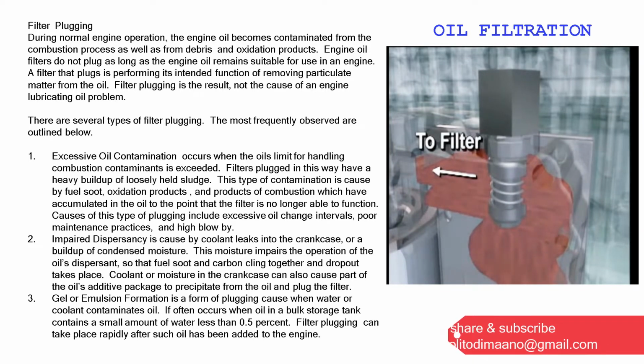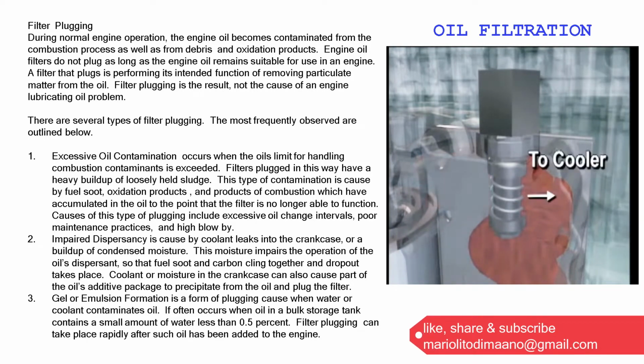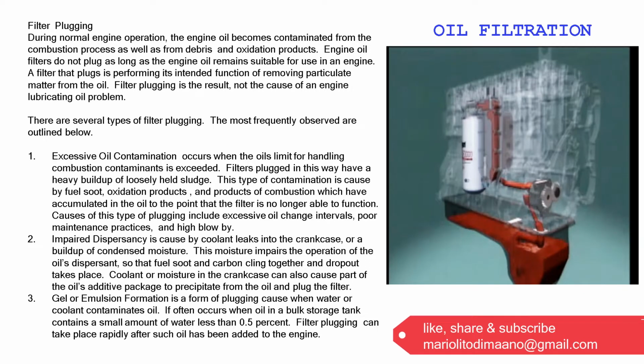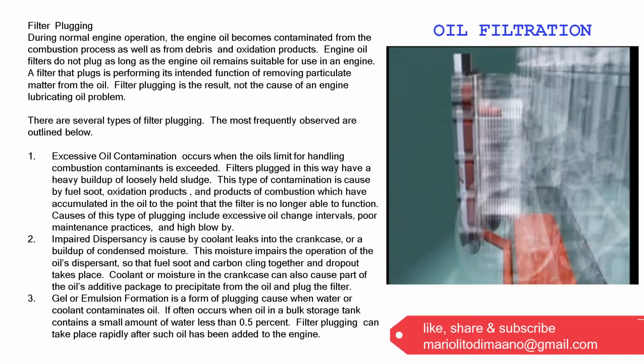There are several types of filter plugging. The most frequently observed are outlined below. 1. Excessive oil contamination occurs when the oil's limit for handling combustion contaminants is exceeded. Filters plugged in this way have a heavy buildup of loosely held sludge.